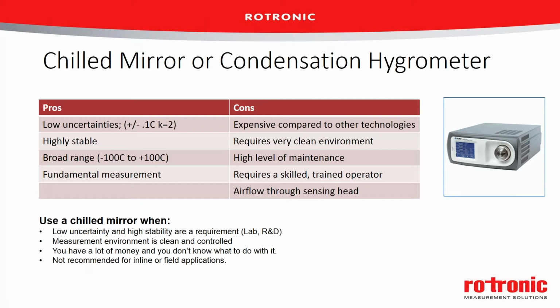And it's that keeping the mirror clean that creates a higher level of maintenance for these devices versus some of the other devices we've talked about today. The mirrors do need to be cleaned on a regular basis and make sure that when they're being cleaned, we're not leaving streaks or other things behind. And so this can require a skilled operator to be the person taking care of and using the chilled mirror. We also need to make sure we've got steady airflow through the sensing head. Otherwise, we don't know what's going on in the environment around us.